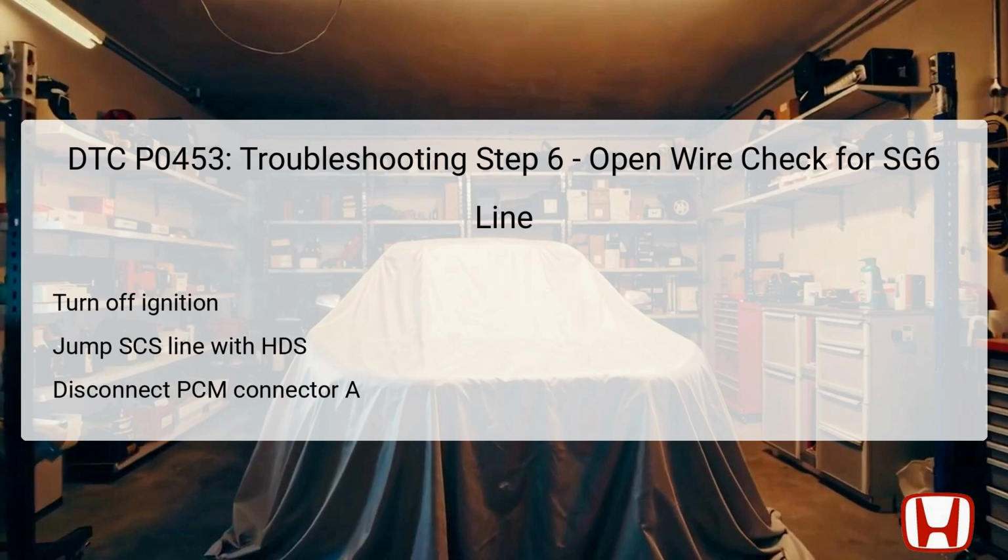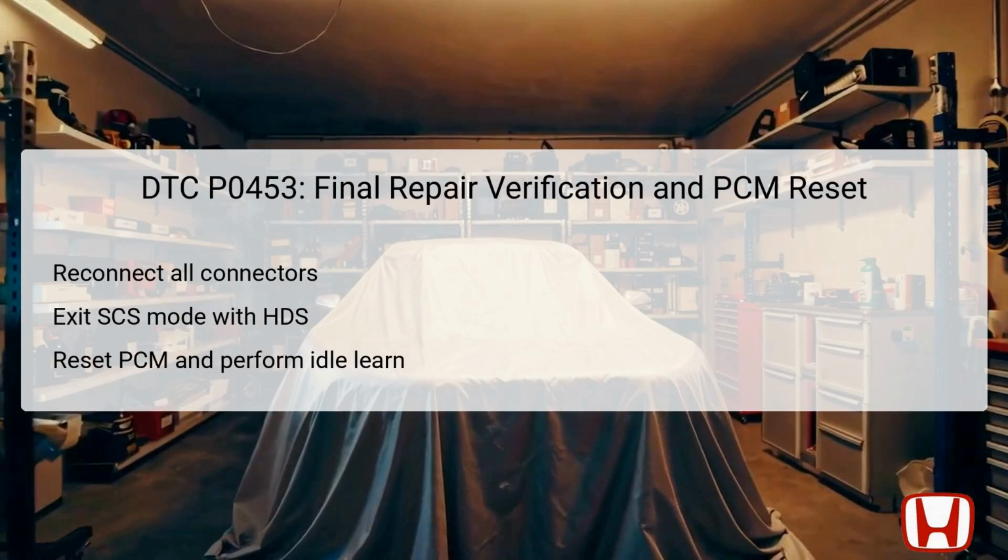You then verify continuity between the PCM terminal and ground with a multimeter or continuity tester. If you find continuity, the wiring pathway is intact, indicating no open circuit in this line. If there is no continuity, you need to repair the open or damaged wiring. Confirming wiring integrity ensures that signals and power are correctly transmitted, which is critical for accurate sensor readings and proper circuit function.